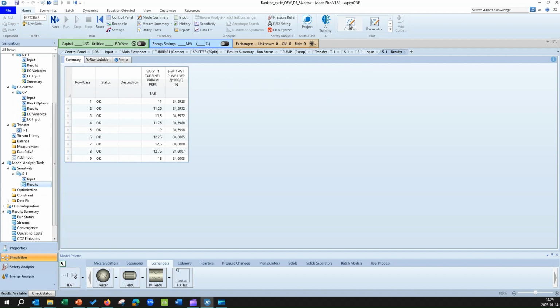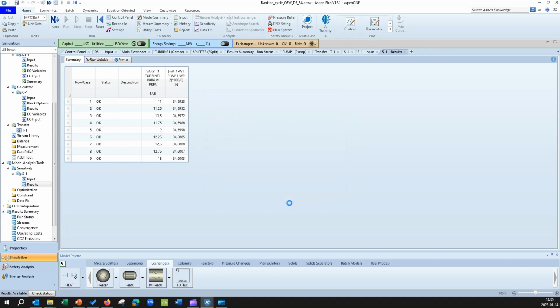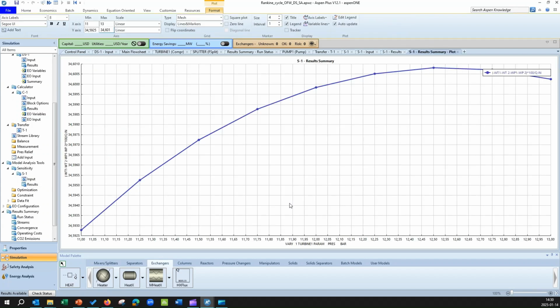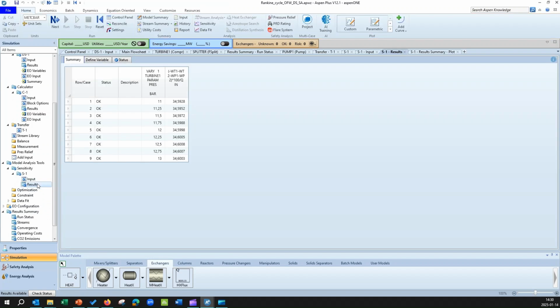So in order to have a better look, we can select the efficiency versus pressure diagram, and we see that we have got a nice curve, and the maximum in this curve is around 12.1 is this point. That's 12.5 this point. So it seems that 12.5 is pressure in which you will get the highest value for your efficiency, and it's around